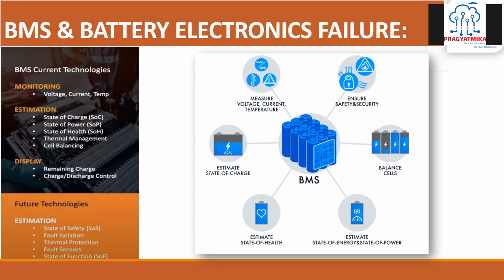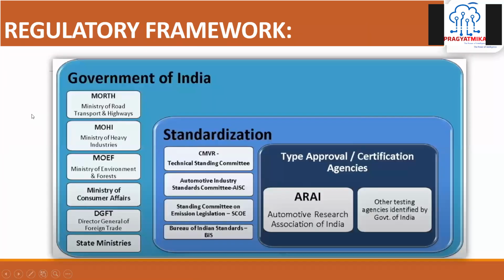What is the curve of the energy delivery that your pack is following? Is the pack going under health, or is the pack being utilized more, or overcharging or undercharging? All this information you can get through the data from the BMS. And this is what we should be looking towards, not just a protection device which does just the cutoff based on the voltage and the current.